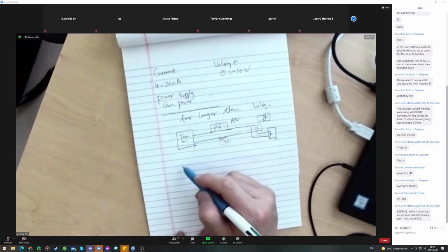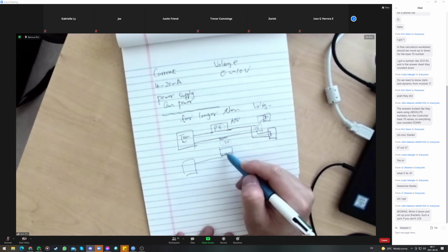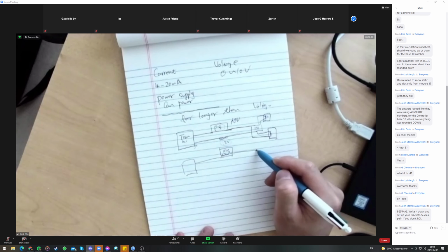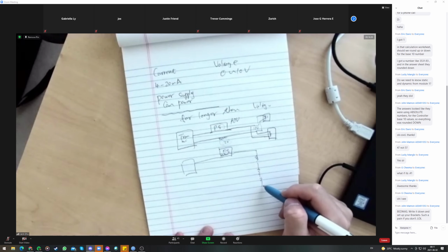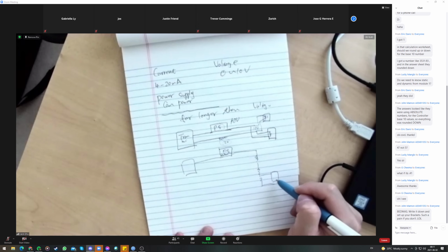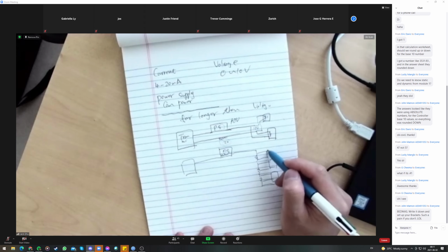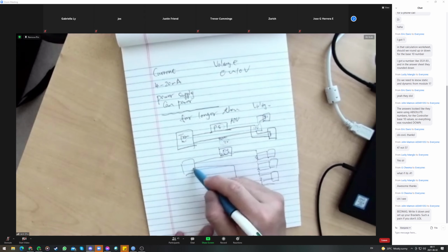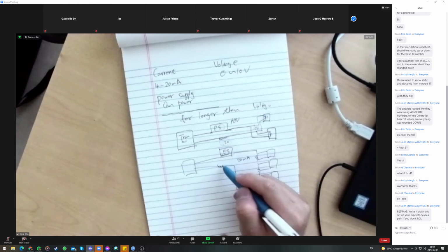But for the current source, as long as your power supply provides a certain amount of voltage, because most of the time you will have a series circuit, your equipment is always connected in series. So you do a calculation for 20 milliamps, and you have a wire resistance.